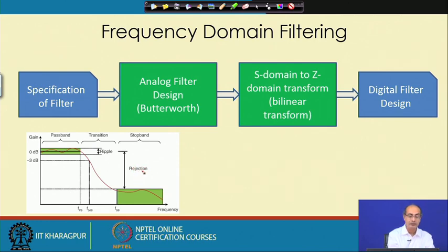Next, some people would like it to be close to the ideal filter, which means there should not be any change or undulation in the pass band. So, they try to control how much ripple there would be. These undulations are called the ripple, and we specify the maximum allowed ripple.